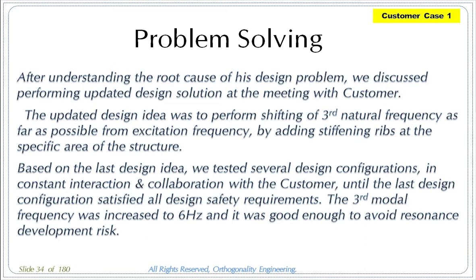Based on this design idea, we tested several design configurations, in constant interaction and collaboration with the customer, until the last design configuration satisfied all design safety requirements. The third modal frequency was increased to 6 Hz and it was good enough to avoid resonance development risk.